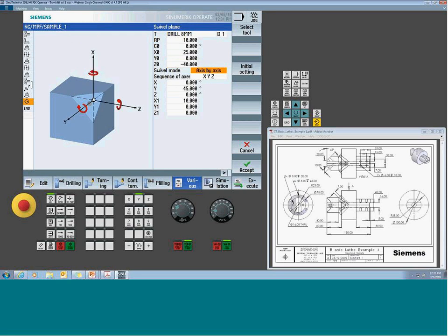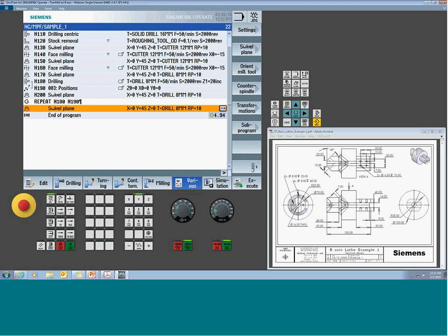Right? She comes back to do a rotation of 45 degrees positive. That puts the X, Z coordinates right here, so X is moving back to the surface. Z is now partly out off the surface, walking across the part. And I want to do a final shift to the center of my bolt hole per my print, of positive 7 mil in X. That's going to plug that X, Y, Z coordinate system right there on the hole location. From there, we can start our feature.